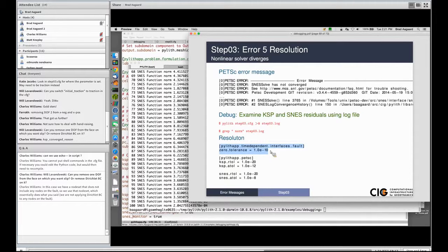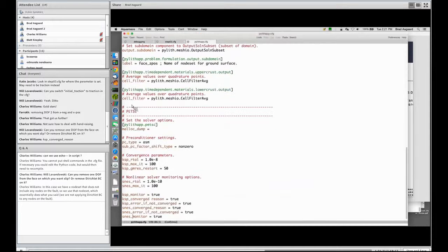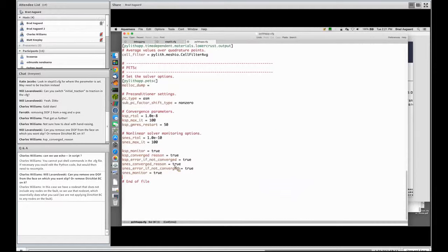That's forcing our displacements and velocities to be less than that zero tolerance. So here are some convergence tolerances. Let's stick those in the bottom of our .cfg file. I've got to clean this up a little bit from the cutting and pasting.